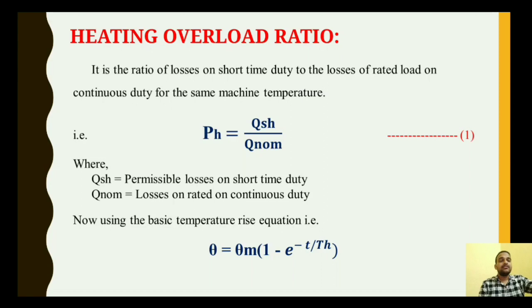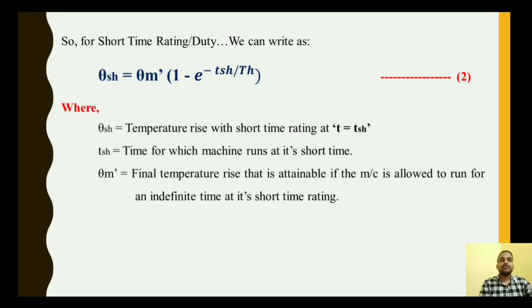Again moving forward, for the short time rating duty we can write, as we have seen, the basic equation of the machine temperature rise, that is theta equals theta m in bracket 1 minus e to the power minus t upon Th.